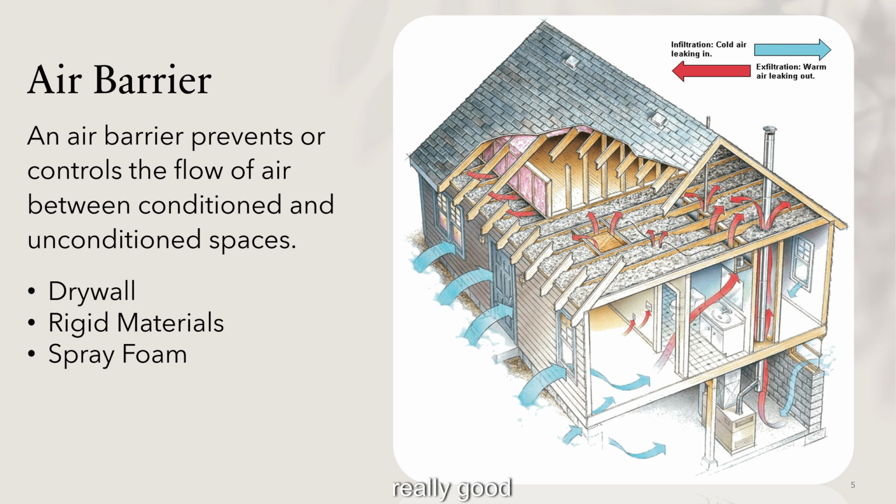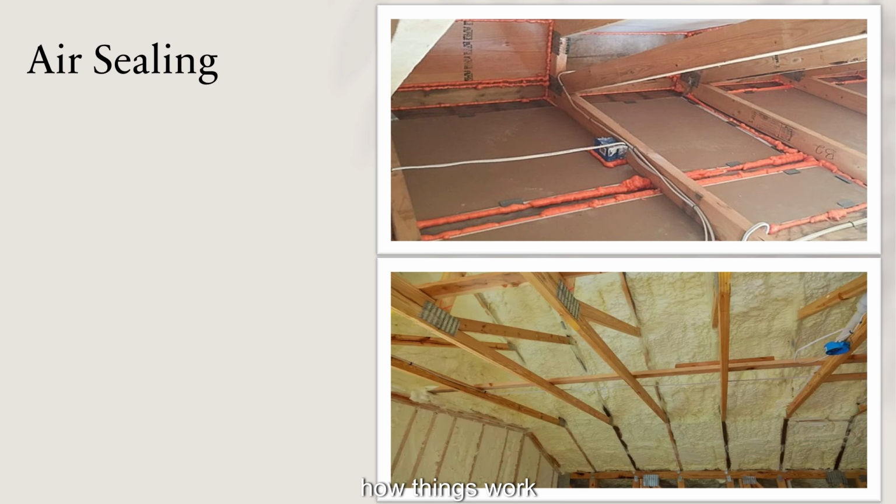Spray foam, really good, fantastic product. However, you just have to be careful with it. If it's overdone, it could cause some major issues. Some people are trying to create conditioned spaces up in their attics. They just figure, hey, it's another space, and so they're going to spray foam the ceilings and so forth, and now all of a sudden it becomes part of the square footage of that home. So that's one of those things that we have to understand and know when it comes to building design and load calculations. Spray foam will have a big impact on how things work.